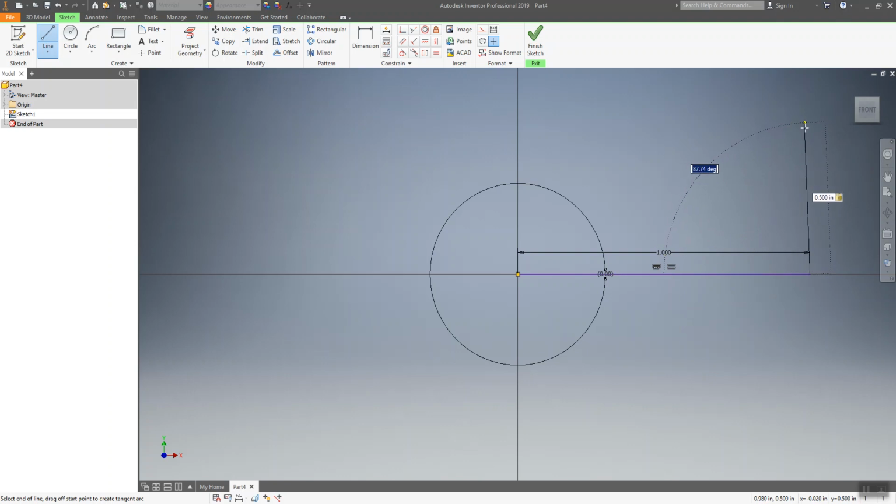So now I'm going to make this one a 90-degree angle and press enter. And so now every time that I do that, it's going to create a constraint, a dimension constraint, and we'll talk more about those later. So I'm going to right click, escape, and that takes me out of my line command, and now I have created two lines. So I'm going to undo that, and let's learn a little bit about splines.